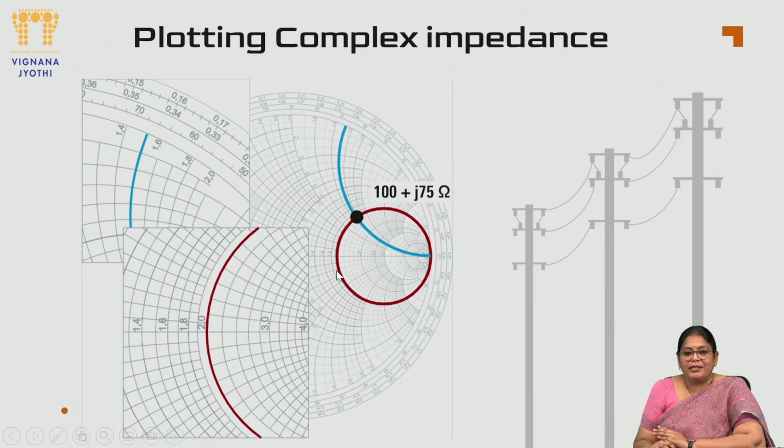So you have to take the resistance circle which is passing through the value of 2, and similarly 75 by 50. Okay, 75 by 50 is 1.5. So 1.5 is the reactance value where I have to take my curve. The reactance curve has to be taken from the 1.5 value and all the way running through the resistance axis where it is the origin point.